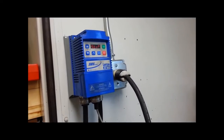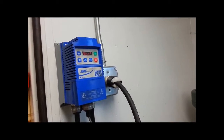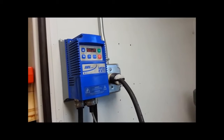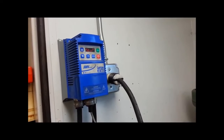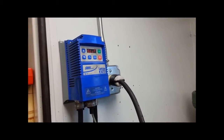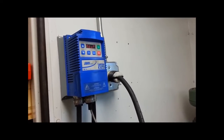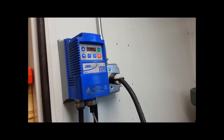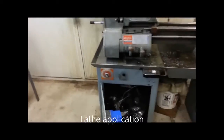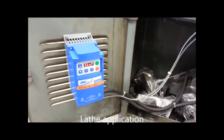That's the one on my mill there. That is a single-phase input, or technically it's a polyphase input. That would be 2 hot legs. So it's 2 phases. But 2-phase is not a recognized term. It's also known as polyphase. So that's 2 phases of input and 3 phases of output, and that's a 2 horsepower rated unit. Down here on the door of the lathe, I use that one to variable speed the lathe.